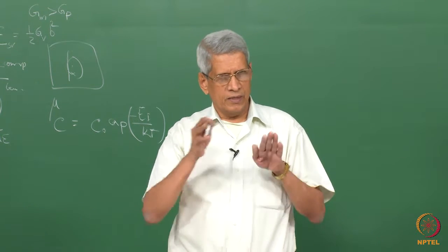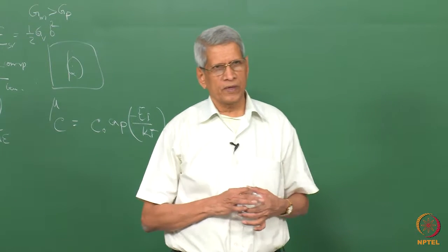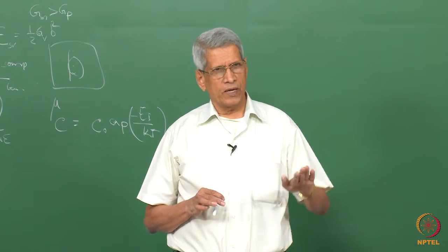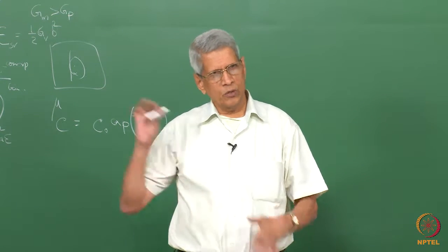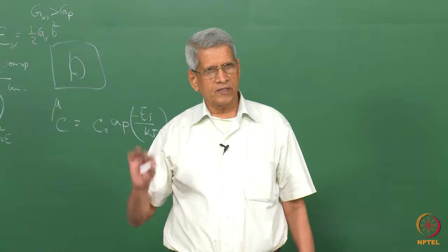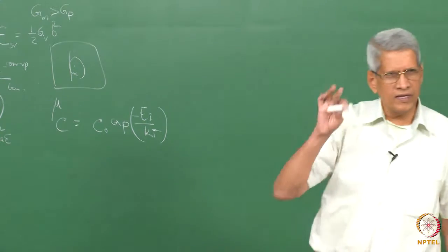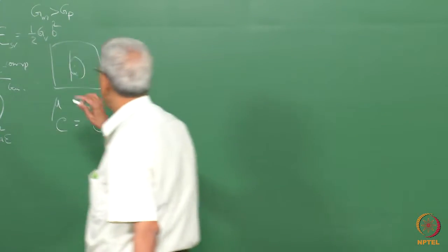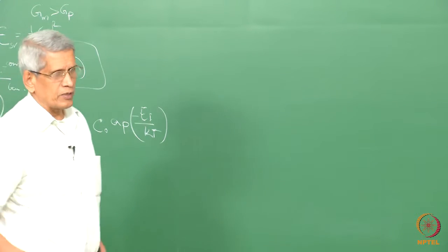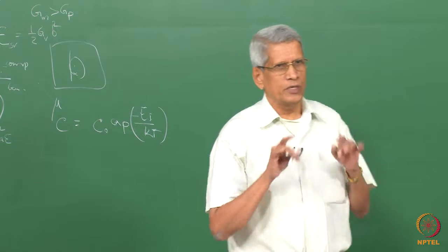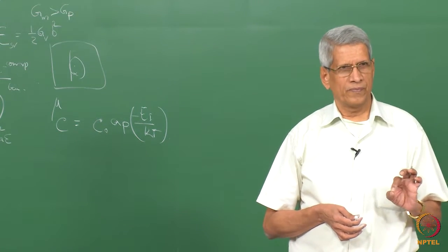Generally this happens at temperatures less than 0.5 Tm, where diffusivity is sufficient for impurities to migrate, but at the same time the thermal vibration is not sufficient for the atoms to escape. So there is a net increase in the concentration of the solute around this location. If this sort of impurity atmosphere forms, this is what is called a Cottrell atmosphere.